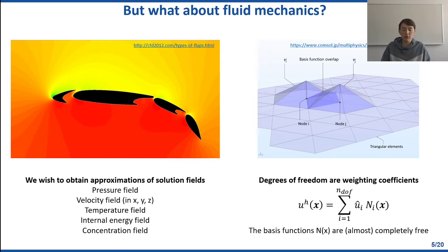Specifically for finite element methods, we typically have these localized shape functions that are also illustrated here, defined by these elements on a mesh. And that is almost the exclusive way that we're going to think about our elements. They are merely a tool for creating shape functions. So we're not going to think about them as blocks of material that have a certain stiffness. No, we're going to think about them relatively mathematically as just a framework for building shape functions, such that we can write some arbitrary function u as the sum of coefficients times these functions.